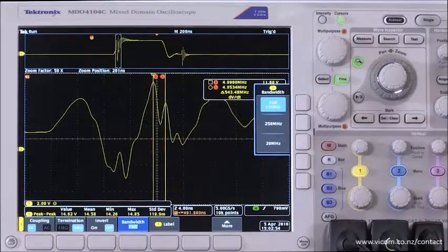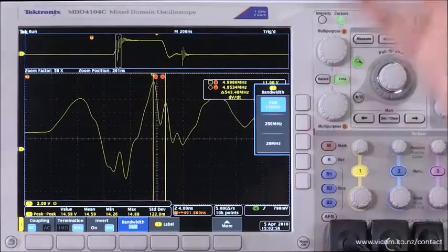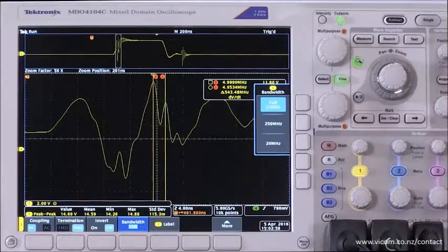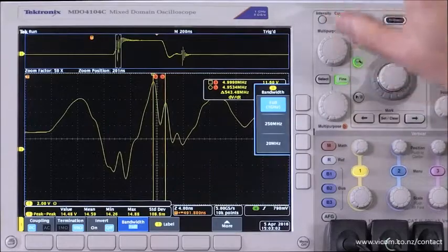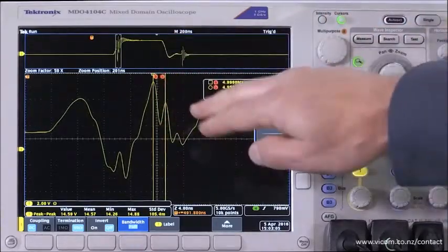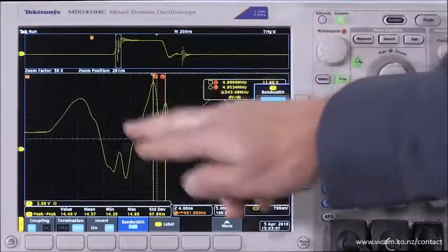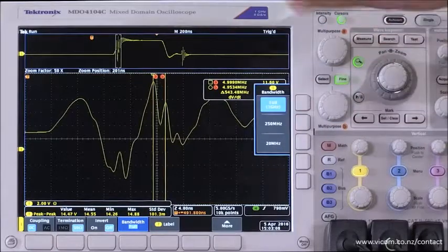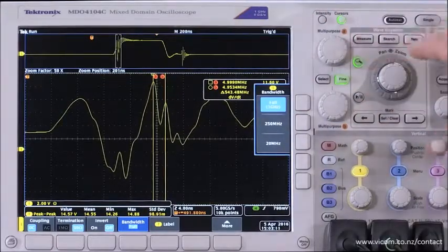So with that 20 megahertz measurement system before, invisible. 250, I see a hint of something, but I don't know what it is. A 1 gigahertz system, I can actually get in there, see that it's a 500 megahertz ring on top of my 100 megahertz resonance, and allowing me to go through and figure out in my circuit, the devices, what's causing